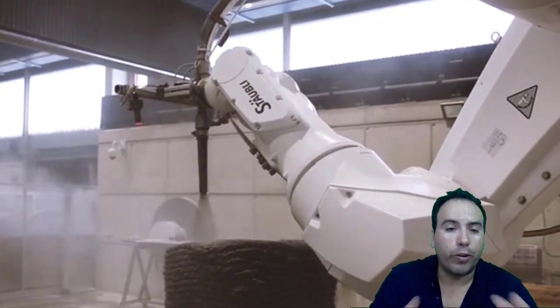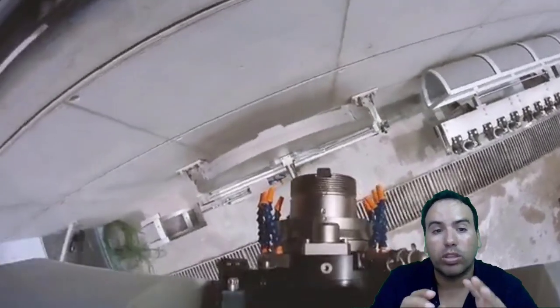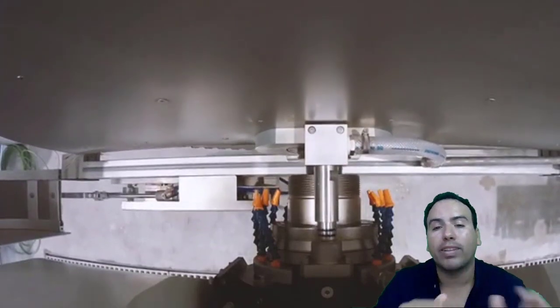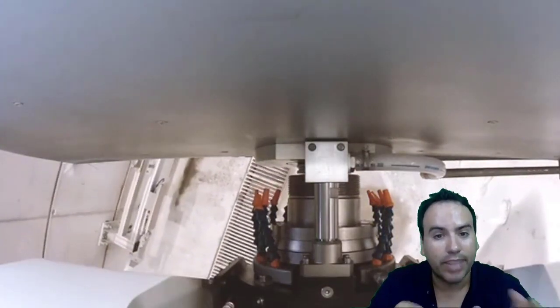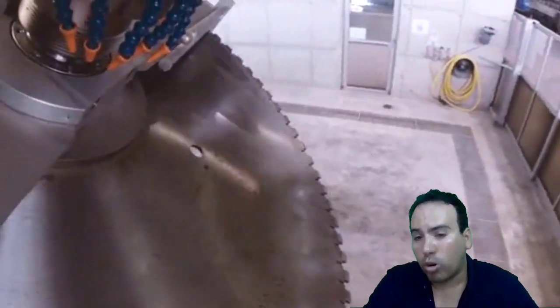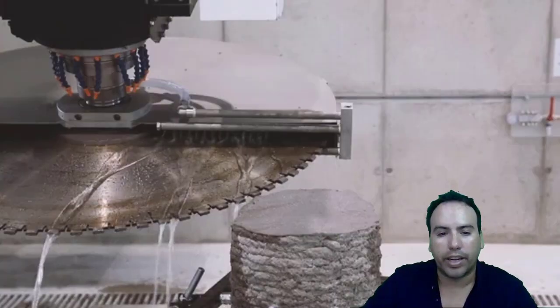Now, footings. Footings are structural elements that transmit the load of the entire superstructure to the underlying soil below the structure. Footings are designed to transmit these loads to the soil without exceeding its safe bearing capacity, thus preventing excessive settlement of the structure beyond a tolerable limit, to minimize the differential settlement, and to prevent sliding or overturning.